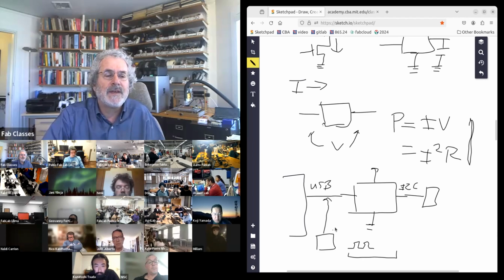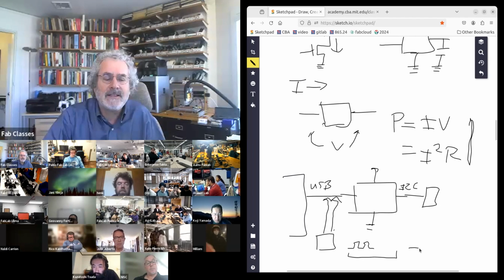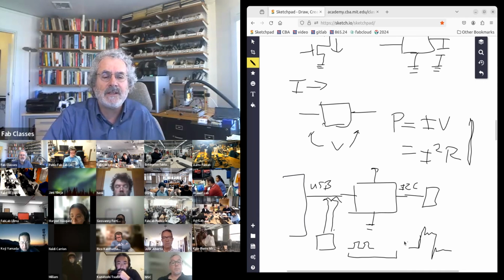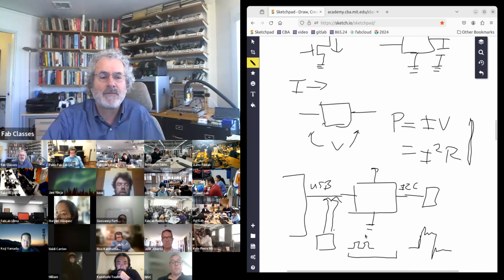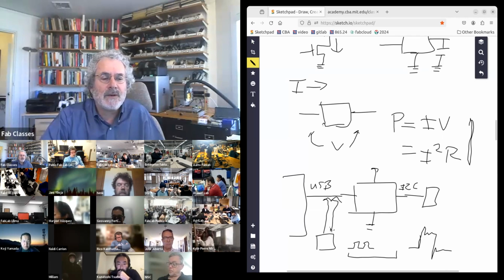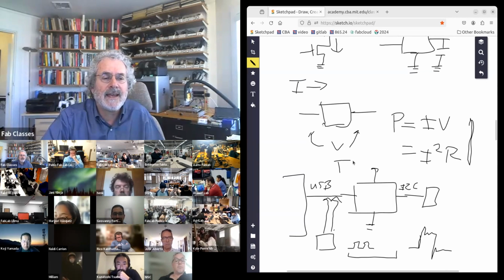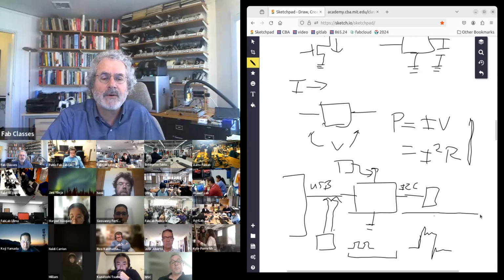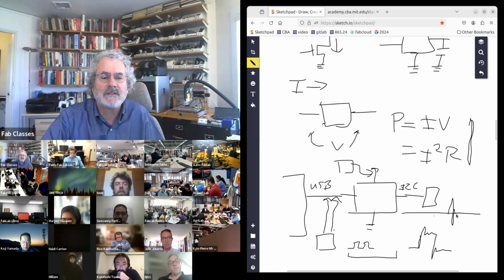Then if you use an analog scope to look at it, what you will actually see is instead of a sharp transition, you'll see some ringing and some overshooting and stuff like that. And you can see eventually when that gets bad enough, you have trouble with the signals. And so in turn, if you connect an analog scope to your power supply, what should be a clean power supply, you might see when, for example, a power transistor switches, you'll see big surges of noise on the power supply.